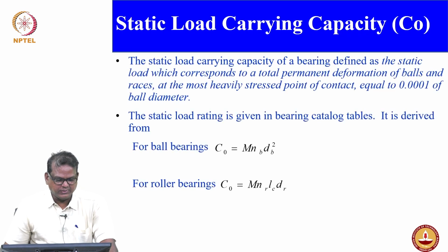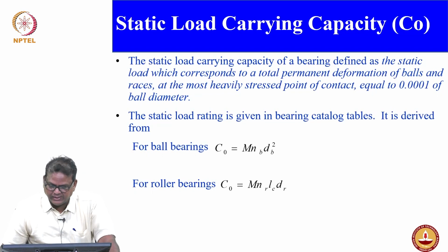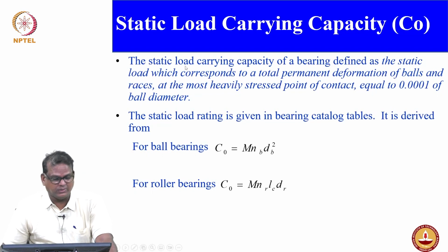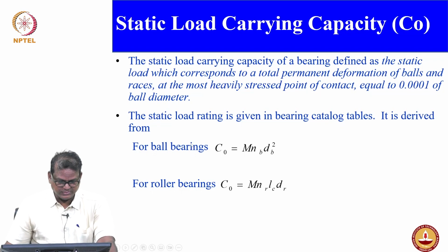Load carrying capacity, the static load carrying capacity of bearing is defined as the static load which corresponds to a total permanent deformation of balls and races at the most heavily stressed point of contact should be equal to 0.001 of the ball diameter. This is the standard equation.